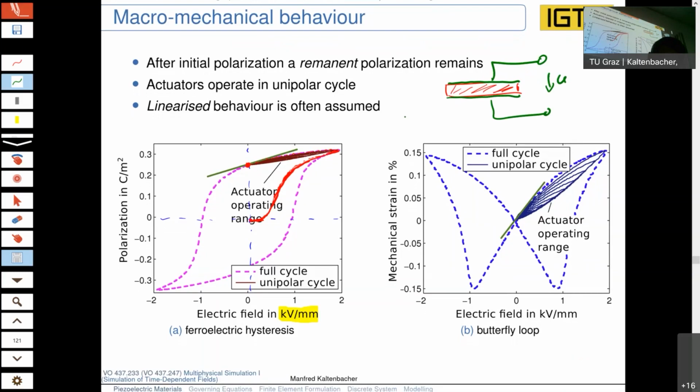Yeah, and we know simply the electric field is voltage over distance, where the distance is just the thickness of our piezoelectric disc. Okay, and that is important, that we get, as shown here, this remnant polarization. Yeah? And clearly for materials used in such actuators, we want to have this remnant polarization as high as possible.